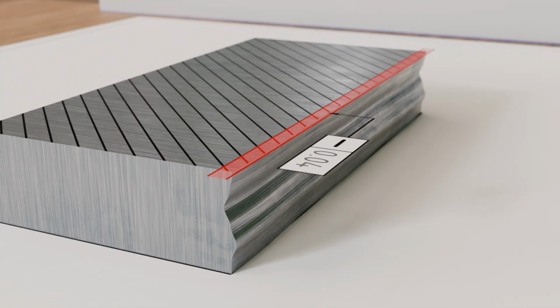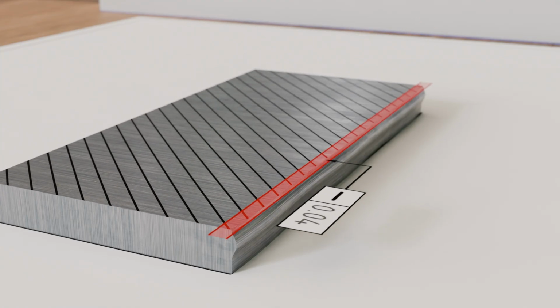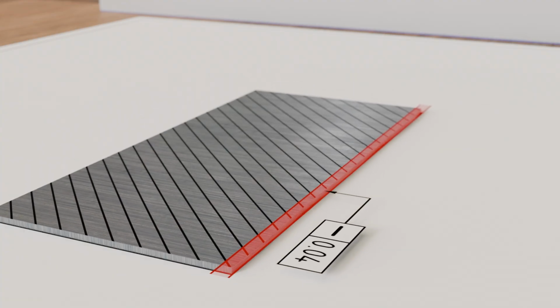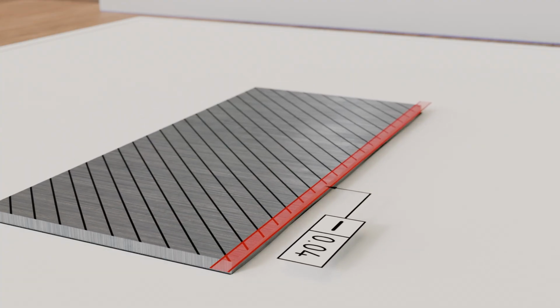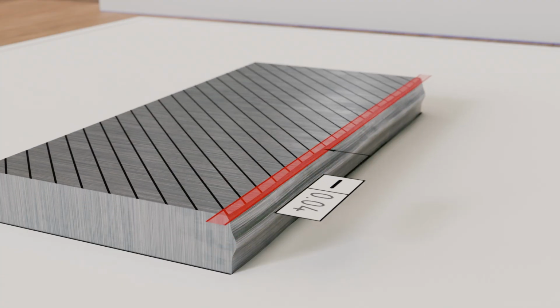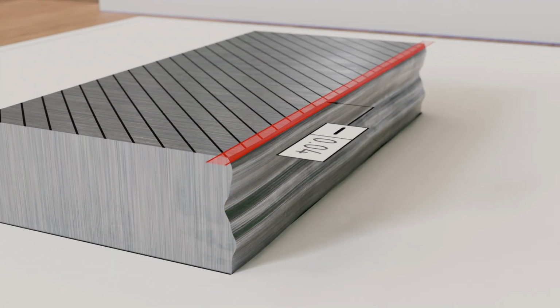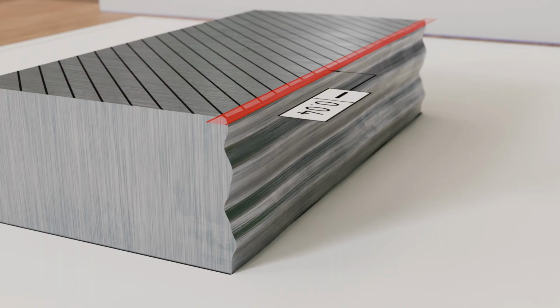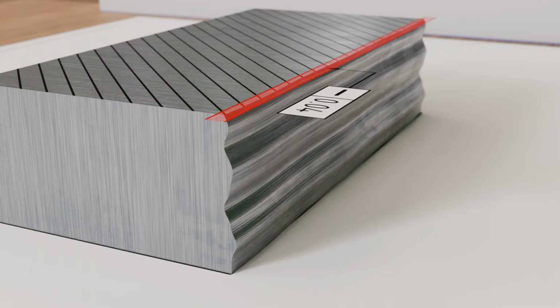It should be noted that in some cases it can make perfect sense to specify straightness on a surface instead of flatness. This is because straightness is inherently one-dimensional, whereas flatness applies to a two-dimensional area. As a result, the manufacturing and inspection effort for flatness is higher, since straightness effectively needs to be satisfied in two perpendicular directions. Therefore, if the part's function allows it, specifying straightness instead of flatness on surfaces can be a practical choice.